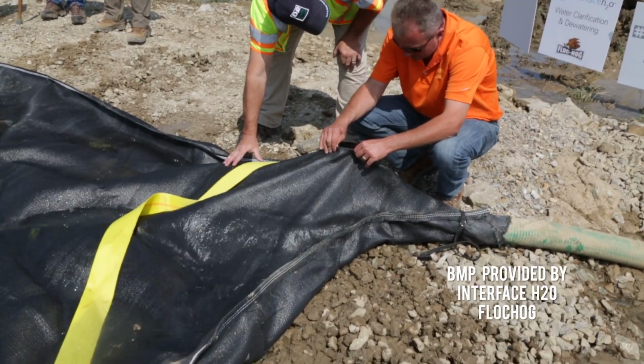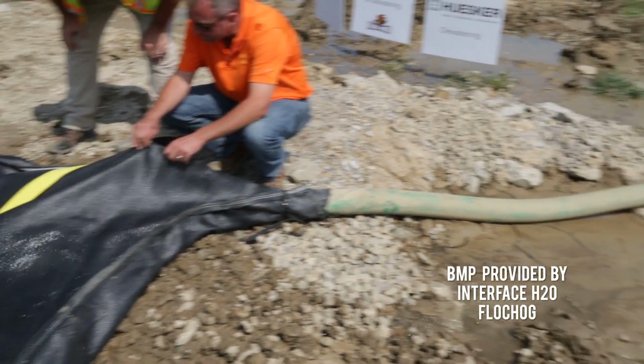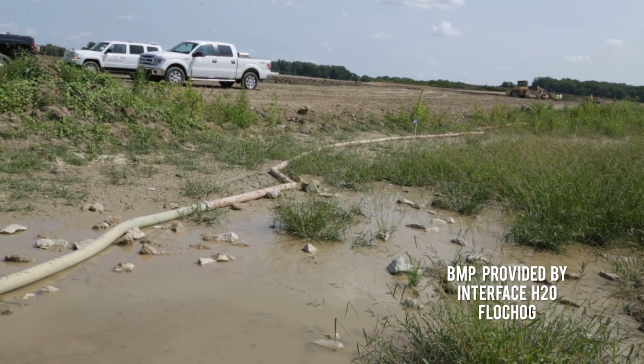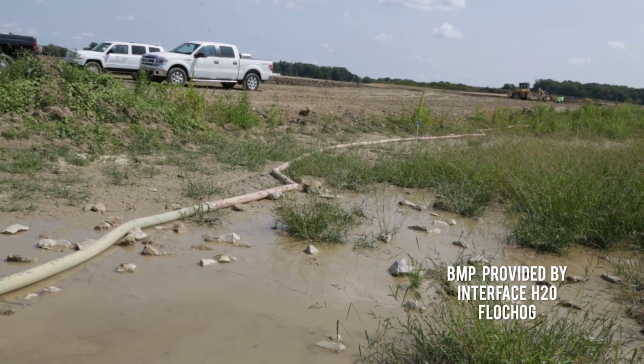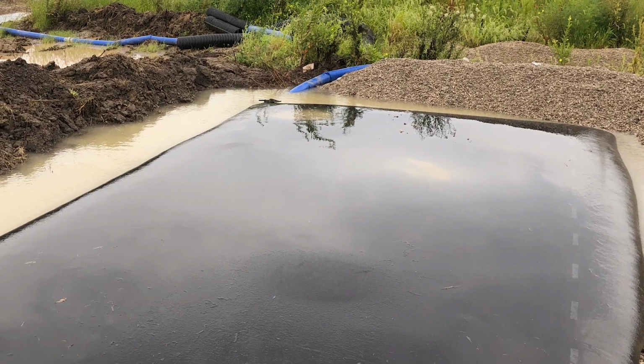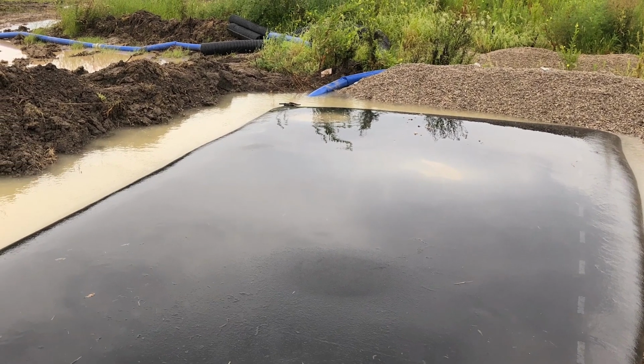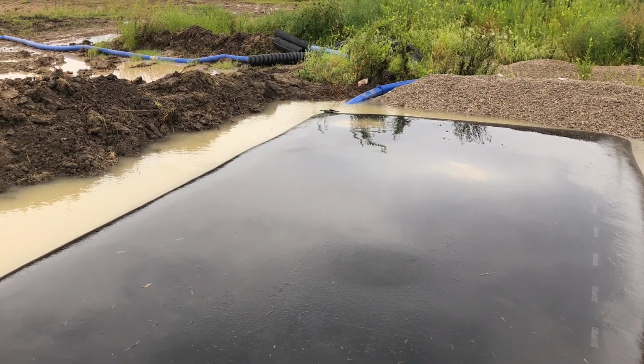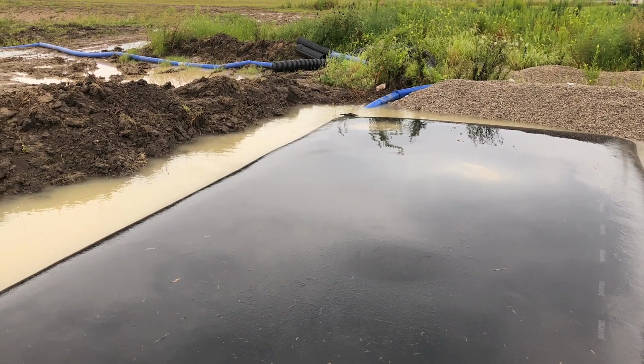Water volume and dewatering rate calculations are performed to determine appropriate erosion control, sediment, and flocculant capture and containment within the construction limits. When BMPs are no longer needed, the contractor shall exercise extreme care during the removal stages to minimize the loss of soil sediment and debris that was trapped during construction.